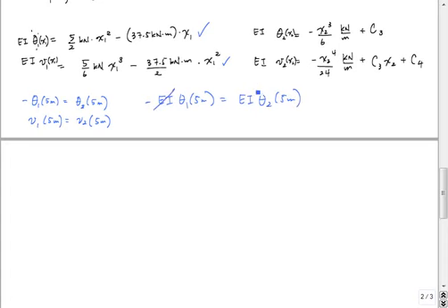You can see the EIs, because they're constant, are going to be the same, so they just cancel out. To solve for C3 now, I'm going to go down to the other page. This will be 5 halves kilonewtons times 5 meters squared minus 37.5 kilonewton meters times 5 meters is equal to this right here. Oh, I don't want to forget the negative.